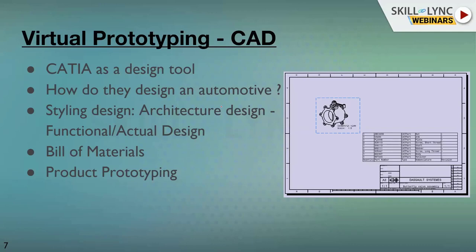Next up, what is a bill of materials? A bill of materials is what you see on the drawing sheet as well. This is the most primitive way of defining a bill of materials. But a bill of materials is nothing but a list of all the parts, the quantity, the name, and the part number of that part. You have different types of bills of materials, but at this stage, you will have what is called the engineering bill of materials, or EBOM. This is just a list of parts that need to go into the product, with the quantity, the weight, and the material defined. So that is what is called the engineering bill of materials. All of this, the entire process of developing the CAD design and generating the bill of materials, prepares the design to be ready to be manufactured, or to pass it on to plan for manufacture.